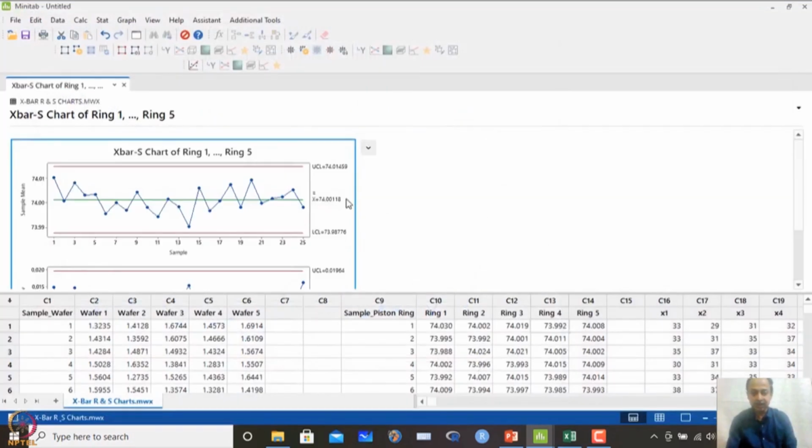In this case the only thing you have to remember is that this type of chart cannot detect small shifts, whenever there is small variation in the process, small shift in the location. For those things we have to use other types of control chart. Okay. Here, when large shifts are there, these are the control charts which are favored, and also we have to understand that the data that we have collected also follows normal distribution. That is another assumption which is considered in these scenarios. Okay. In case that is not true, we have to use some other means to transform the data and then work on that and see the control limits, and accordingly make a judgment whether a point has gone outside or an abnormal scenario is there or not. Okay.